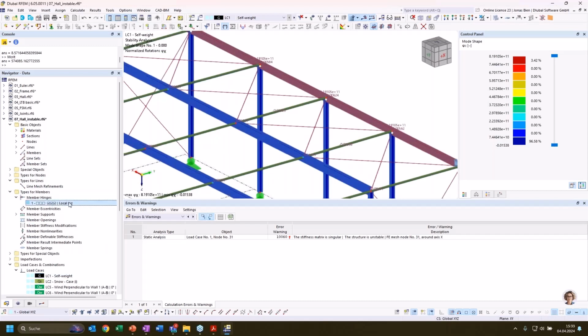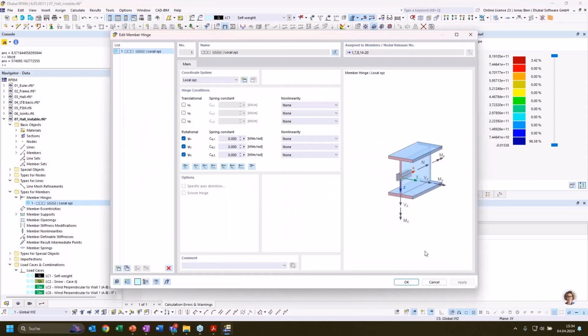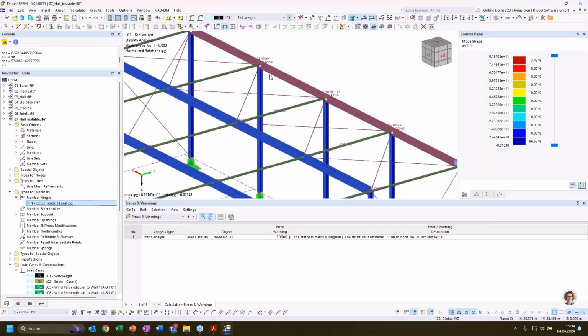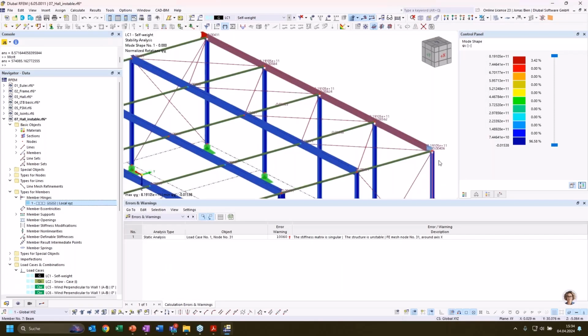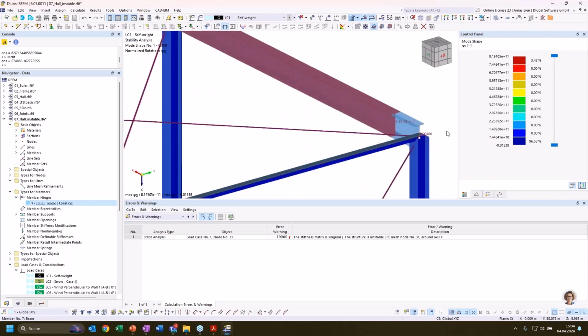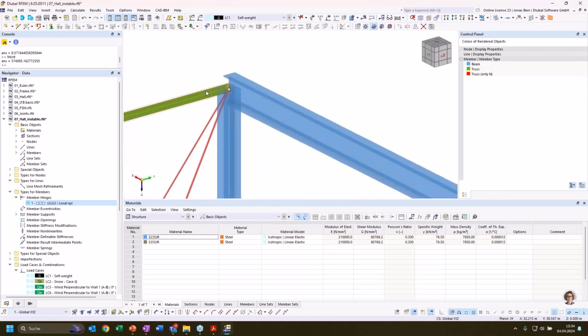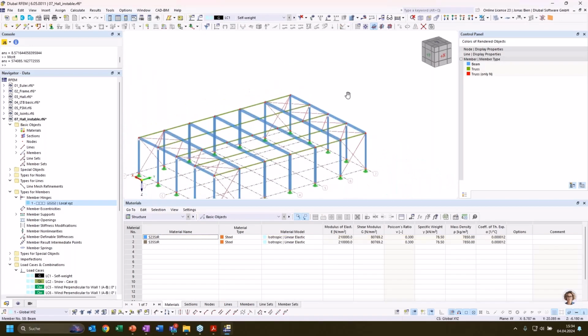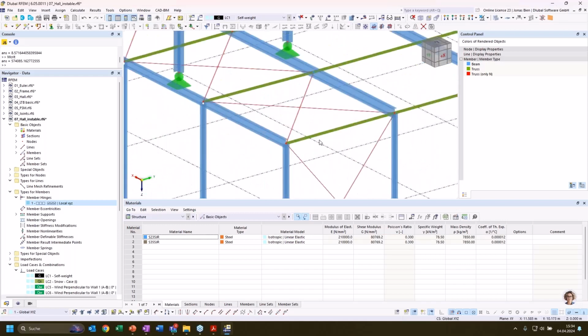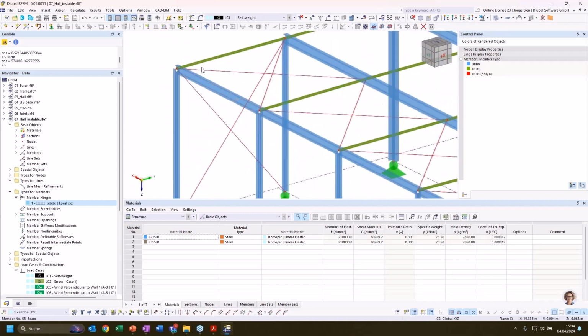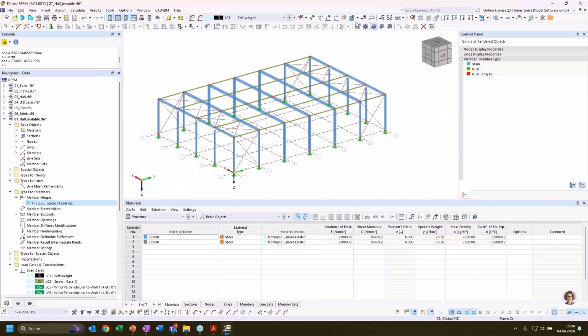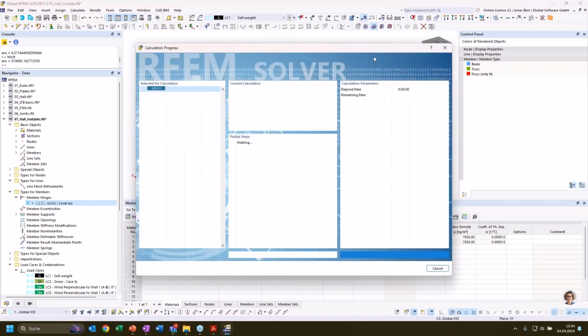I defined this hinge with rotations, or I set free all the rotations in all 3 axes, which means, of course, this member can freely rotate at the top. So maybe that was a mistake, and I wanted to establish frame action here, but I accidentally applied the hinges to all my columns. Now that I found this mistake, I can remove those hinges in the frame corners, and now check a third time if the solution runs or if the simulation works.